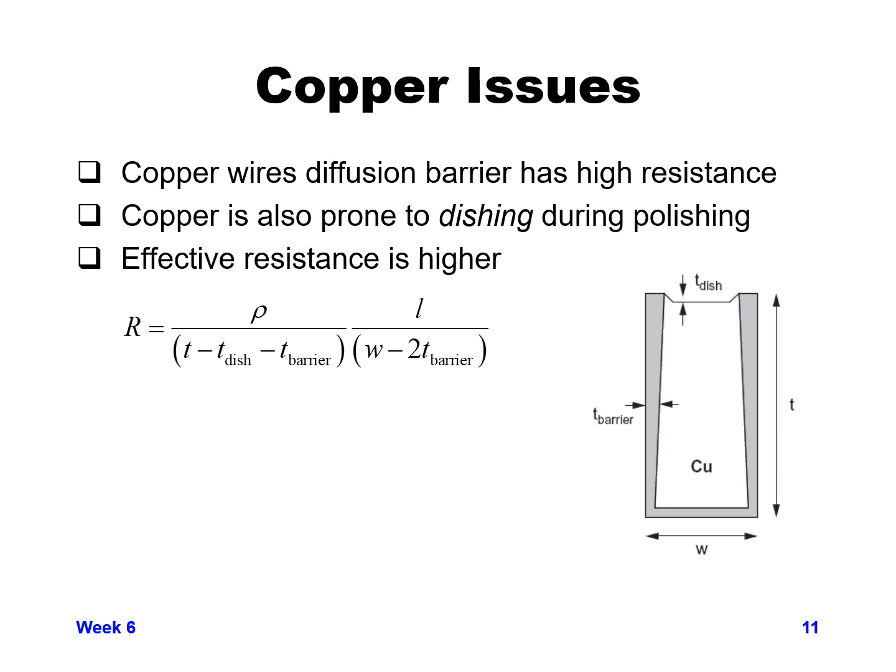And in addition, copper tends to be prone a little bit to dishing. When you're going through the chemical mechanical polish, the very top edge of the copper wire isn't completely flat. It might wind up having a little bit of a dip in the top, and so you lose a little bit of the height of your thickness.